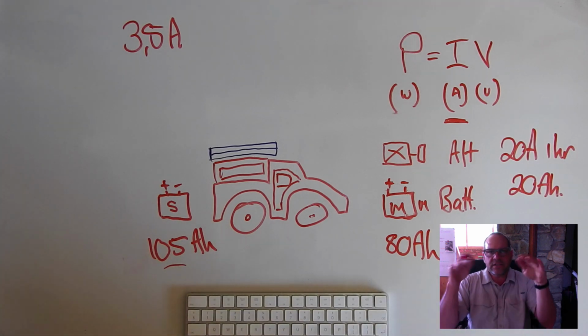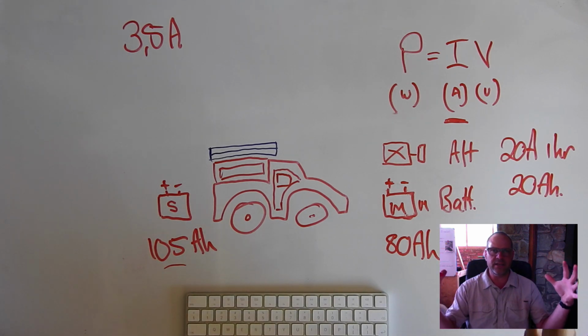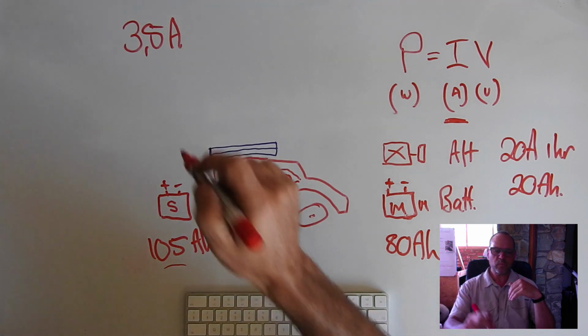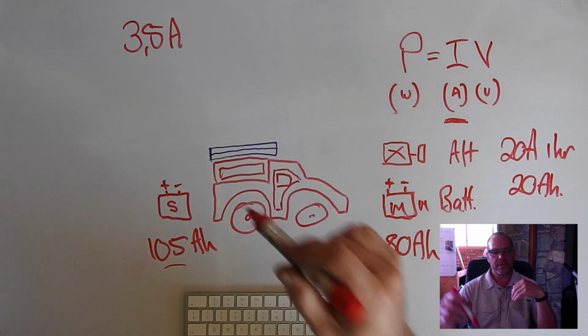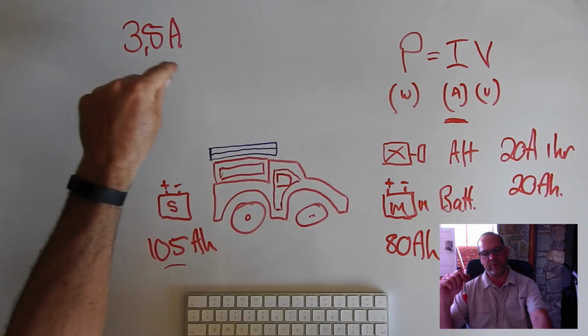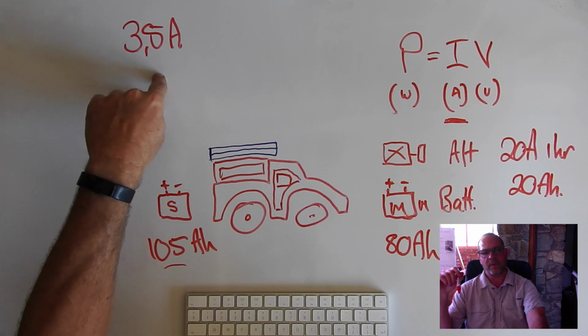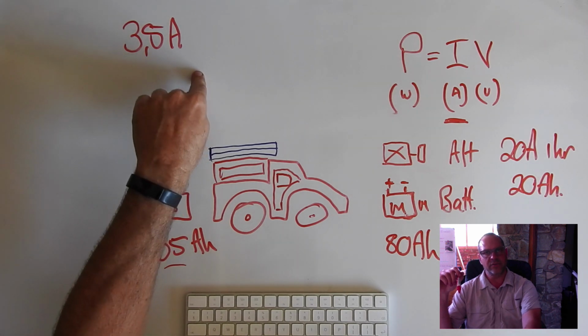So if I have just a little thin plastic skin, obviously the compressor will run a lot longer than if I have nice thick polystyrene sides that protects the cold inside. So the length of time that the fridge will run will give me my amp hours. Now, the current that it draws when the motor is running is 3.5 amps. So if a fridge was running full out, it would be 3.5 amps per hour that it draws.